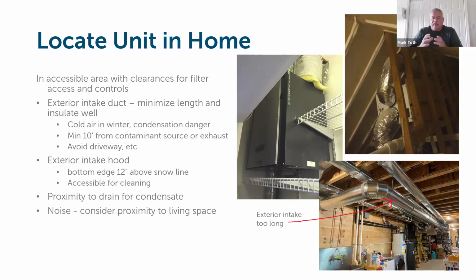With an ERV, some of the manufacturers have core materials, like the one that I'm most familiar with, called a hygroscopic resin. It does not condense. It will transfer some moisture through the material of the core so that it never actually produces water, and it will not freeze. How much humidity does it transfer? That's all variable depending on the conditions.